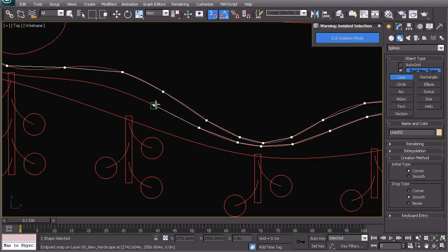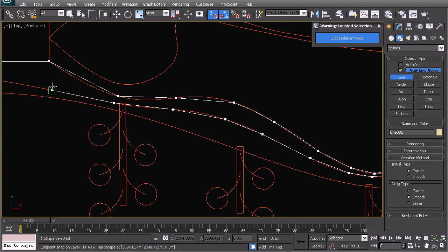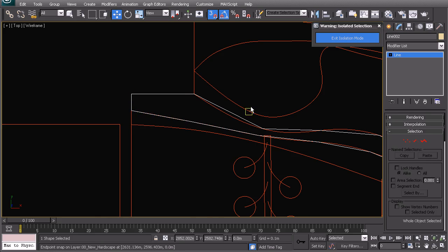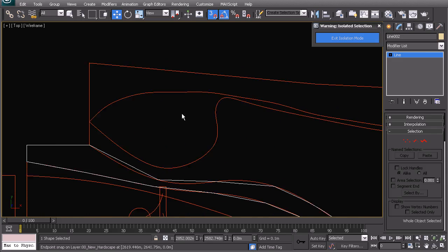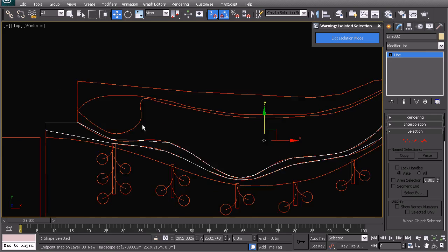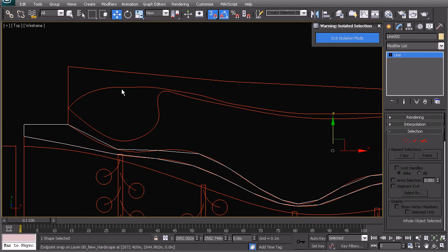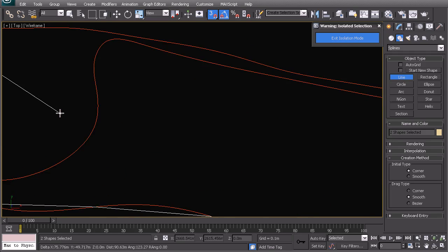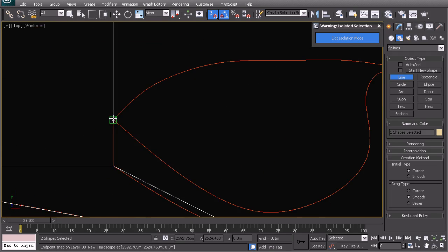Backspace there again. Then we can actually do this one at the back as well. Let's say that all of this is going to be one big garden area as well. So let's just draw another line there. And then here we can untick start new shape so that we have the same. Backspace. Zoom in, and by pressing I, get closer to that.